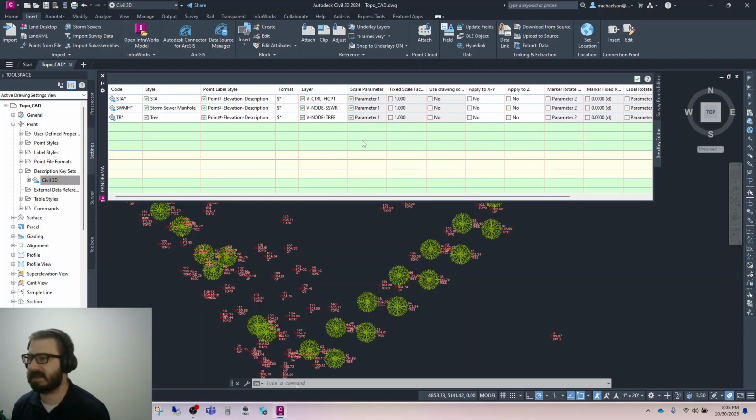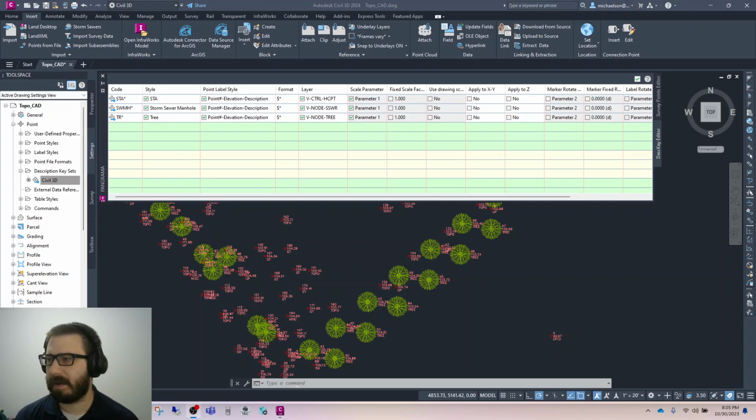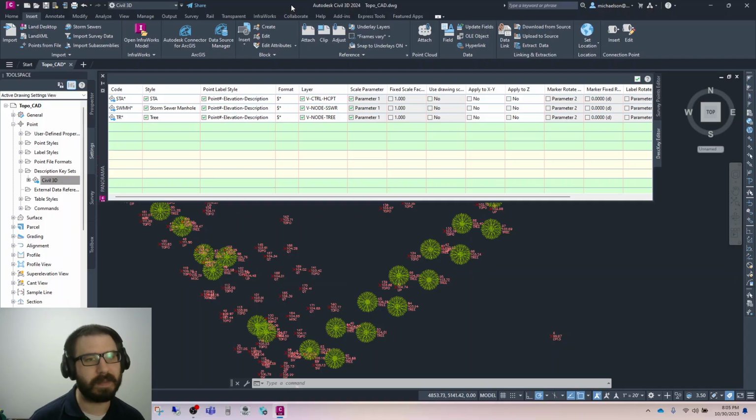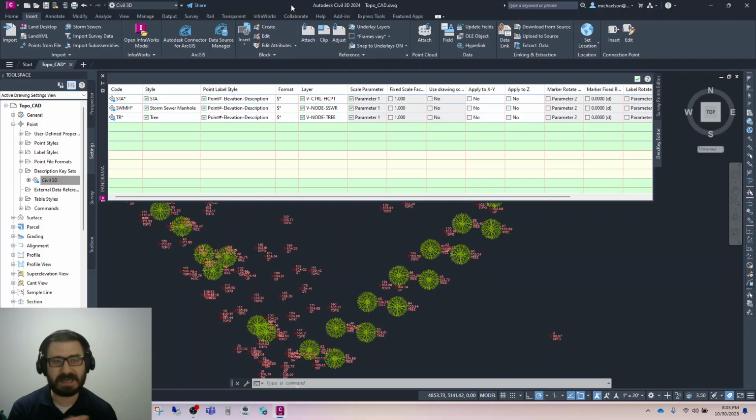Okay, that's probably enough to see what's going on. What we've got here is AutoCAD has basically defined a standard series of formatting steps for it to interpret the data file and then generate a feature in the drawing. For example, we see TR and it says tree. TR star means anything that has a TR or after that, it's formatting as a tree. In my data file, the only thing we coded with TRs was trees. That's why they're all plotting as trees. But there are no real instructions for it to do anything else.